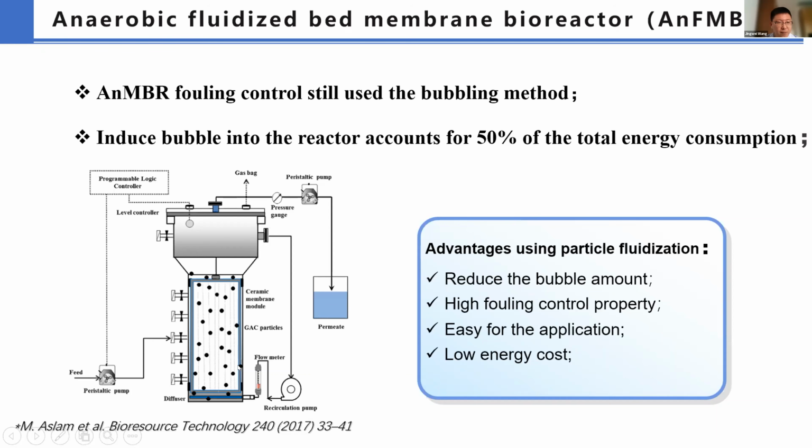This figure shows the typical FBR, where we can put particles in the reactor. Then we use fluid recycling to make the particles fluidize. By using this method, we can control the fouling well, and eliminate the induction of gas, so the energy consumption is low.